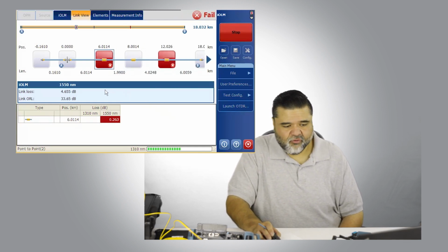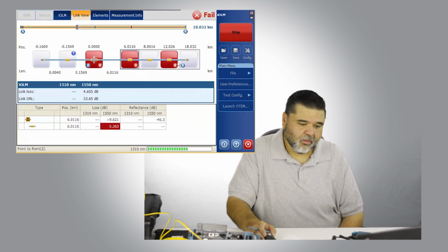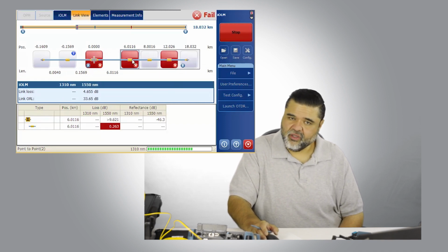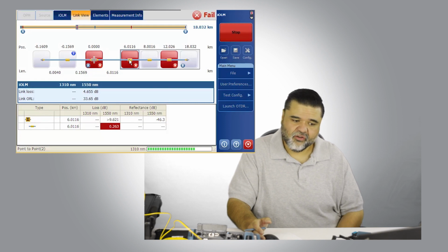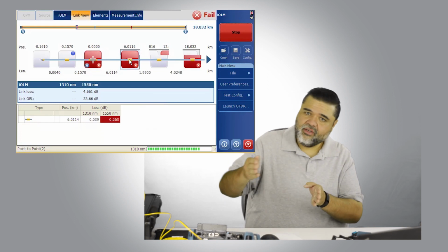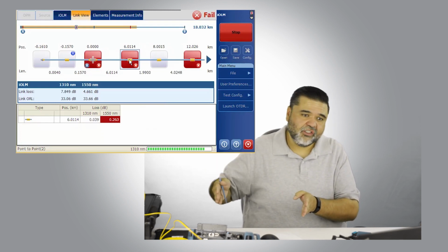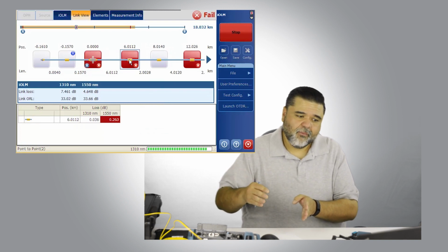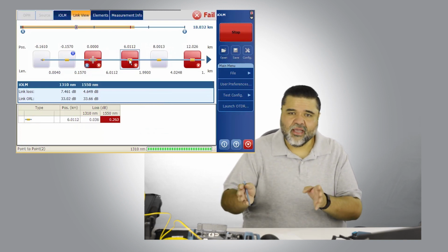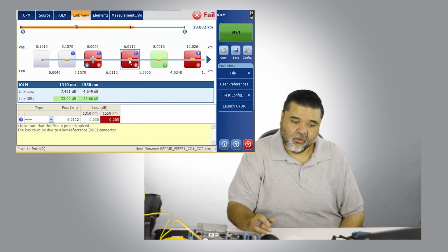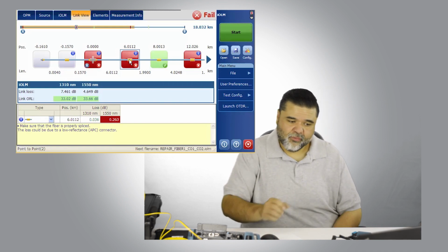And instead of an OTDR graph, we have this block diagram, kind of a linear trace view with all the different elements. And again, you'll see how it changes in real time here as we adjust the different resolutions, you see different results. And so iOLM is going in there, it's shooting a trace at say 5 nanoseconds and 10 nanoseconds. It's cycling through the different resolutions and the different pulse widths, analyzing the information, and then disregarding certain events. So it compares all the different acquisitions and then gives us the analysis based on that. And so now the test is done and we can interpret our information.